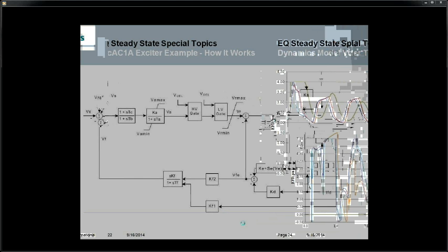so you can define an implementation where you have two phases instead of a full three-phase, or even a case where you may have three-phase, but one of the phases uses a larger wire. Or in the case of transformers, you can actually have unbalanced transformer banks, where you have cases of a small grocery store or a grocery store gas station type of installation.